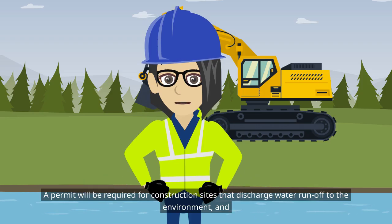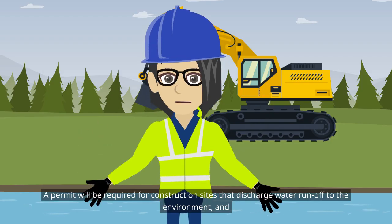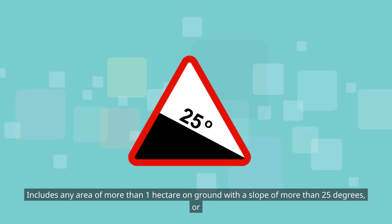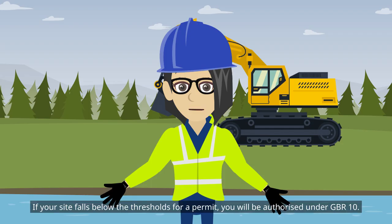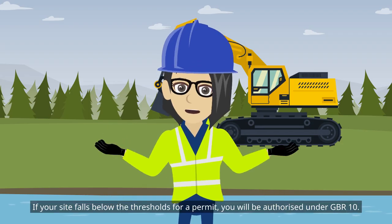A permit will be required for construction sites that discharge water runoff to the environment, and cover an area larger than 4 hectares, or has a road or trackway longer than 5 kilometres, or includes any area of more than 1 hectare on ground with a slope of more than 25 degrees, or includes any road or track longer than 500 metres on ground with a slope of more than 25 degrees. If your site falls below the thresholds for a permit, you will be authorised under GBR 10.